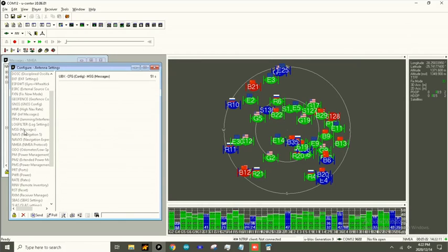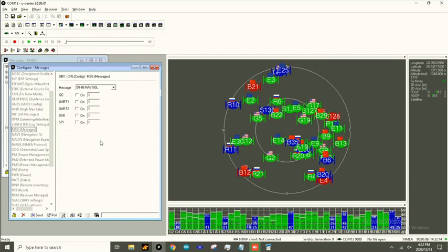So you'll find it over here under messages, and messages describe what kind of data for a particular satellite constellation is actively provided by the GNSS receiver to the u-blox utility program or any other third-party software utility that requires different kinds of messages for specific purposes. So for our working base station or NTRIP configuration, we have to enable a few of these messages which are not enabled by default.